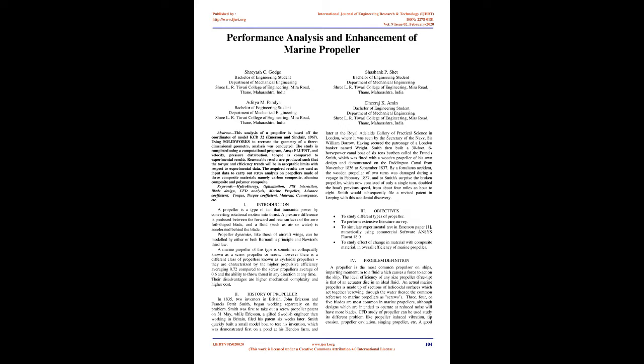However, there is a different class of propellers known as cycloidal propellers. They are characterized by higher propulsive efficiency, averaging 0.72 compared to the screw propeller's average of 0.6, and the ability to throw thrust in any direction at any time. Their disadvantages are higher mechanical complexity and higher cost.